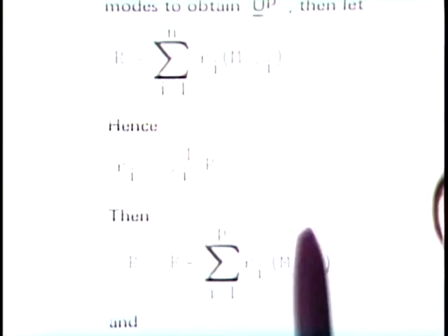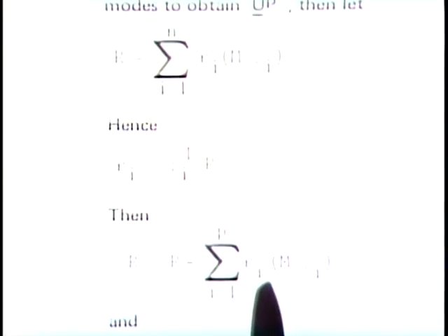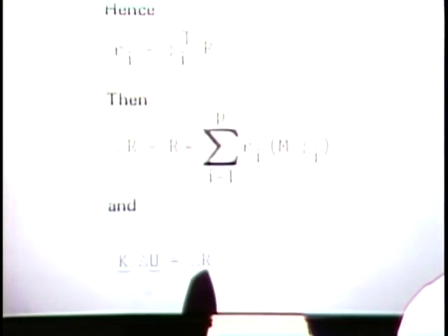But this part is exactly what we have included in the mode superposition analysis already. So we are left with a vector on the left-hand side, which we have not included in the mode superposition analysis. And we did not include it because we knew at most we can have static response corresponding to these loads. Let us now calculate that static response. And that's done right down here. Now, this static response has to be added to the response which we predicted in the mode superposition analysis.